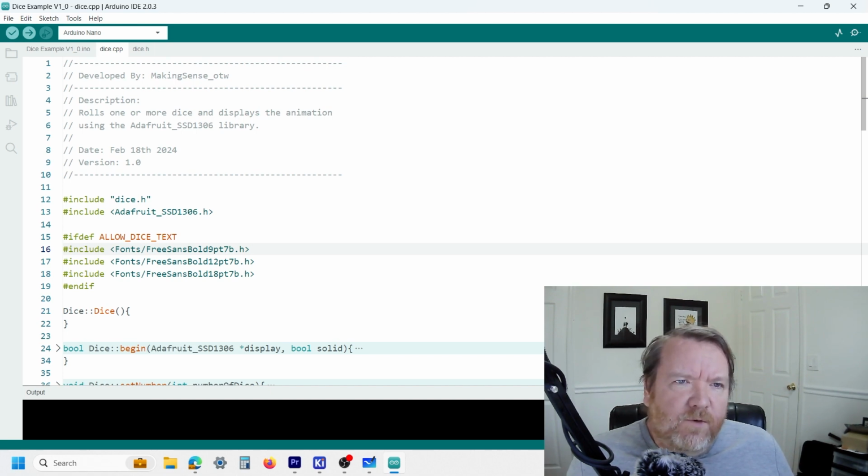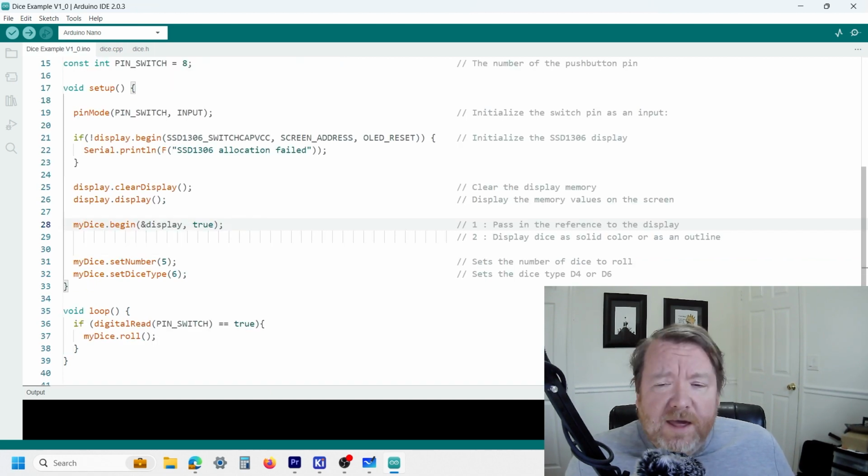So basically, if you fill up all of the memory, what I actually observed was a corruption of the display on the OLED in the bottom right corner. It wasn't giving me an error in the code or any problem like that.